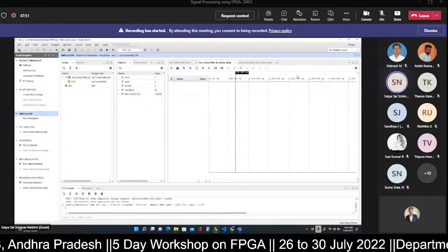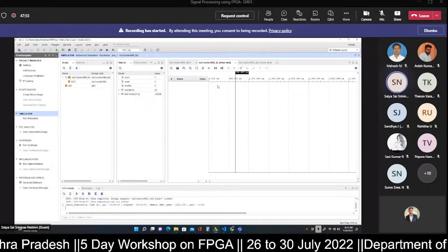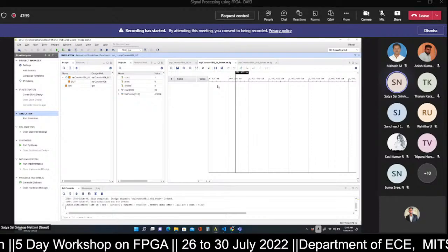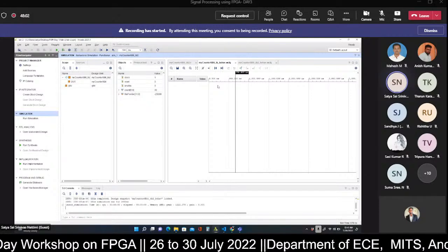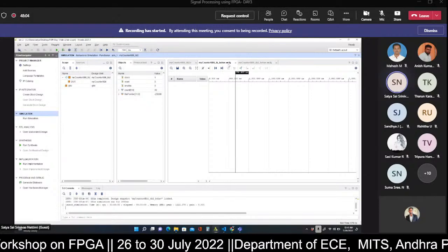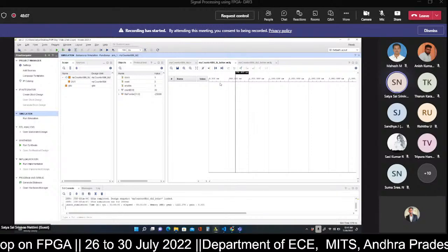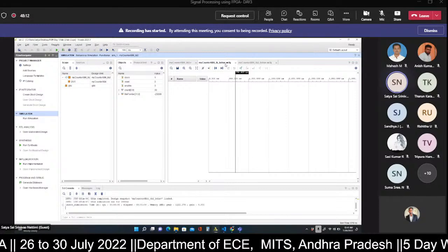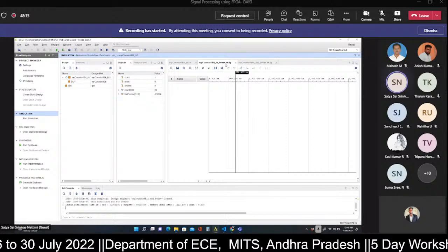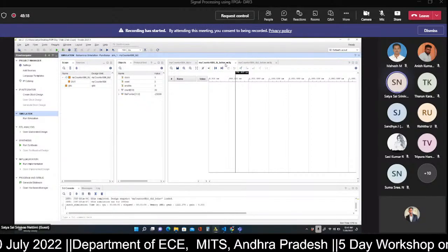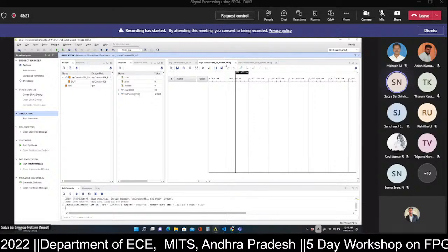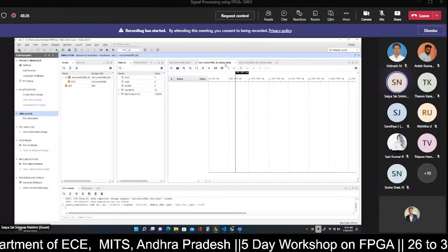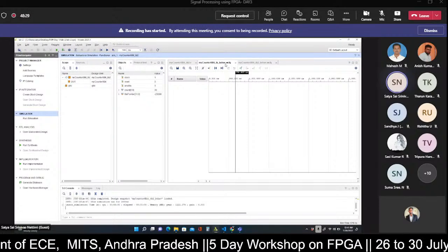And if you remember, once you launched a simulation, earlier we have run our previous test bench. That test bench timing waveform, I think you might have saved. Whenever you launch the test bench, it will open the previously saved file having an extension WCFG. So earlier you saved the test bench file with the timing waveform diagram. Now you have changed it to the new test bench and relaunched it. So it will open the previous file. In that file, no waveforms will be available. It will be a blank file.